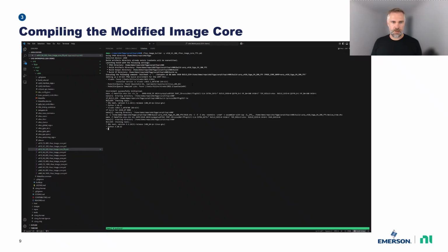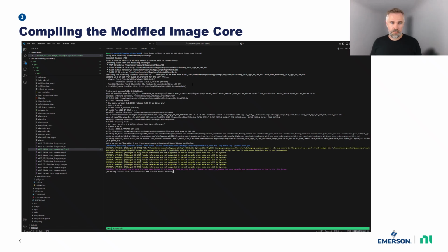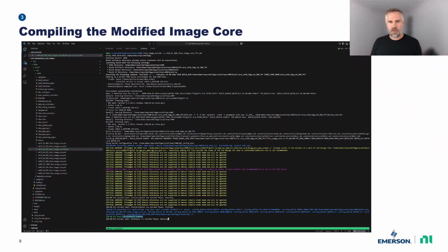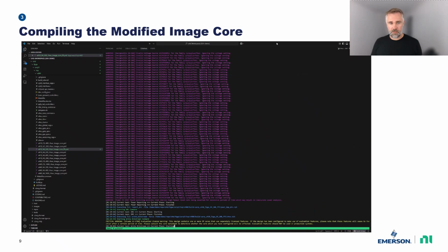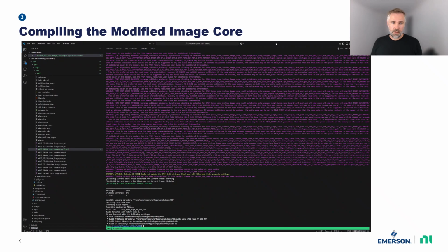Let's start to compile. You can see a number of warnings and some of them are marked critical. This is expected during FPGA synthesis, especially since we develop reusable code for multiple product variants. In Vivado, the classification of warnings, particularly what is considered critical, can change between tool versions. In the meantime, the compile is completed. Let's inspect the results.